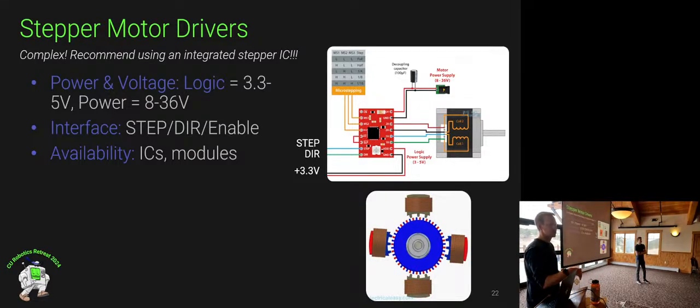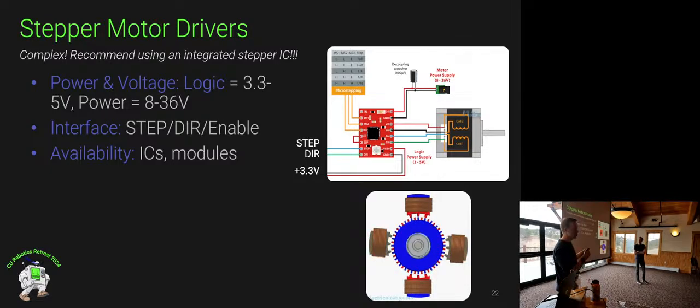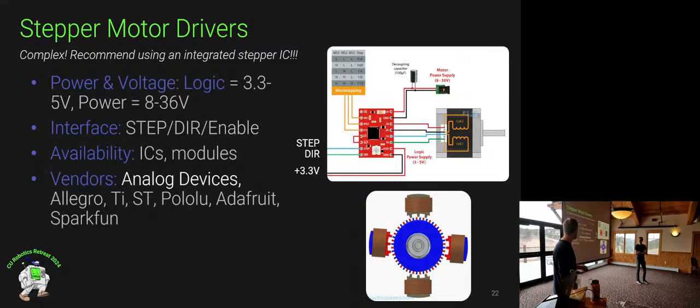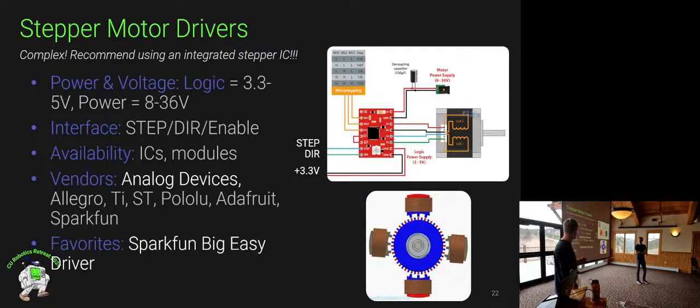Also allowing steps. Yeah, so you can definitely get this one, for example. They have this little interface here where you either pull these signals high or low, and that sets how much stepping you do. So if you're doing a 3D printing sort of thing, maybe you need 1/16th of a step. Basically it's just the resolution that you have for stepping. But yeah, you can do these with almost every commercially available brushless or stepper motor drive.